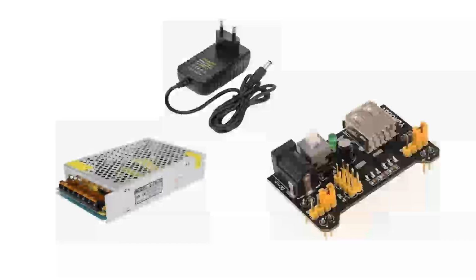Power supply is one of the main elements in every electronic circuit, and the right AC-DC adapter circuit should be chosen if we want our device to accept power line voltage as the main supply. There are several types of AC-DC adapter circuits: transformer-less, non-isolated, step-down transformer, and switched-mode power supply adapter. The schematic diagram of the circuits and how to implement them for our design is presented in this lesson.